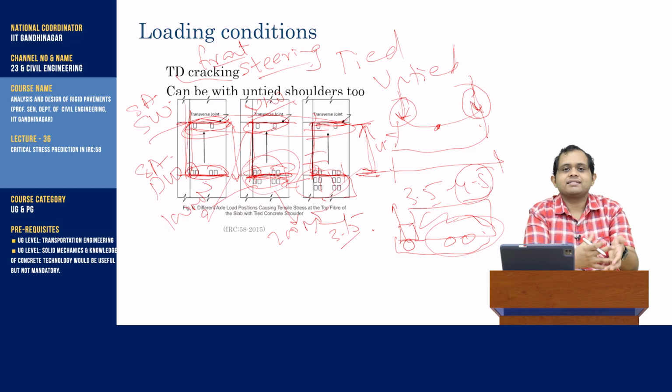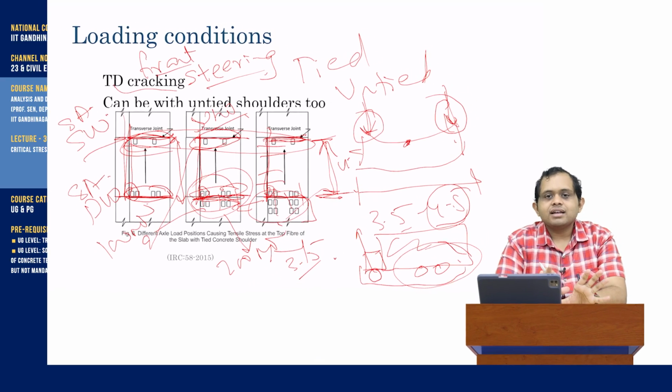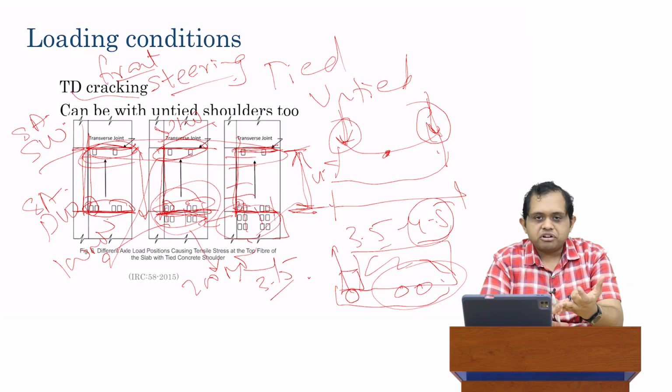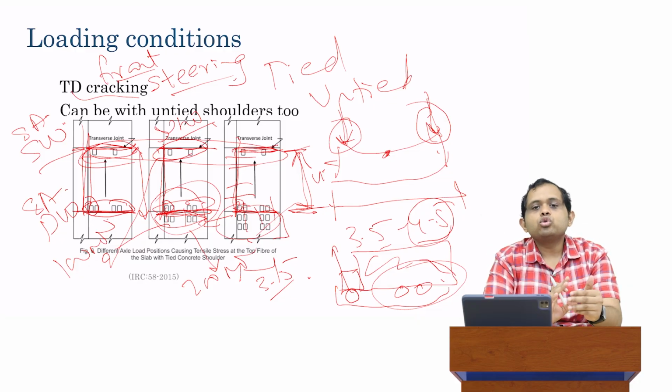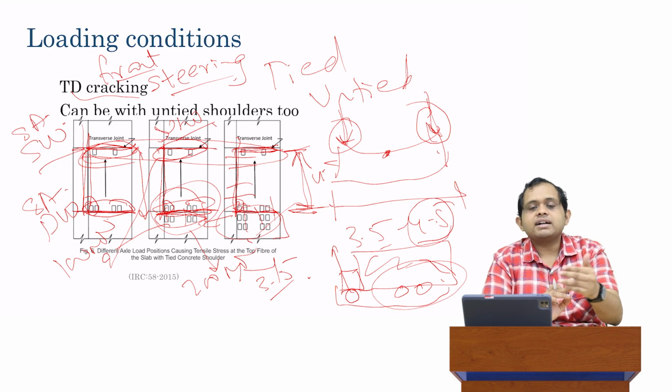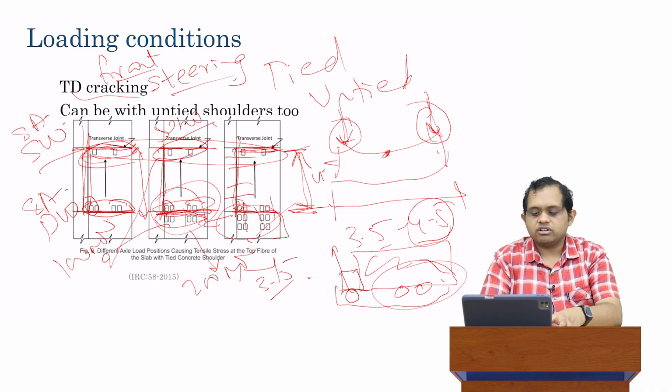What are you carrying? Are you carrying steel? Are you carrying wool? Are you carrying clothes? Are you carrying furniture, etc.? Depending on that, the actual load is going to be different. Whereas the load of the steering axle is basically the engine, the driver, and the driver's personal effects and any other parts of the chassis. Those do not change. So I personally do not agree with the idea that the front axle weight should be a function of the rear axle weight. These two are more or less independent of each other.